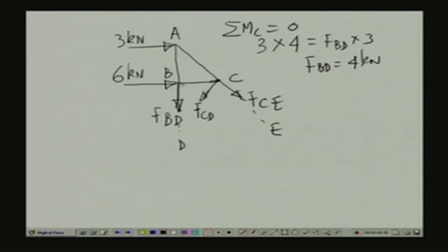And again this is at the joint, it is in this direction. So, in the member the force will be in this particular direction. So, this gives us again a tensile pull. So, this is a tensile force. So, this force divided by the cross sectional area will give me the stress in the member.